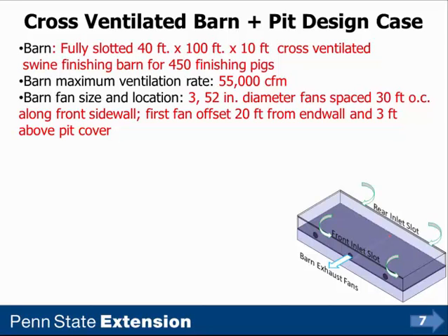The barn fan size and location, we have 3 52-inch diameter fans spaced 30 feet on center along the front sidewall. And the first fan is offset 20 feet from the left end wall.